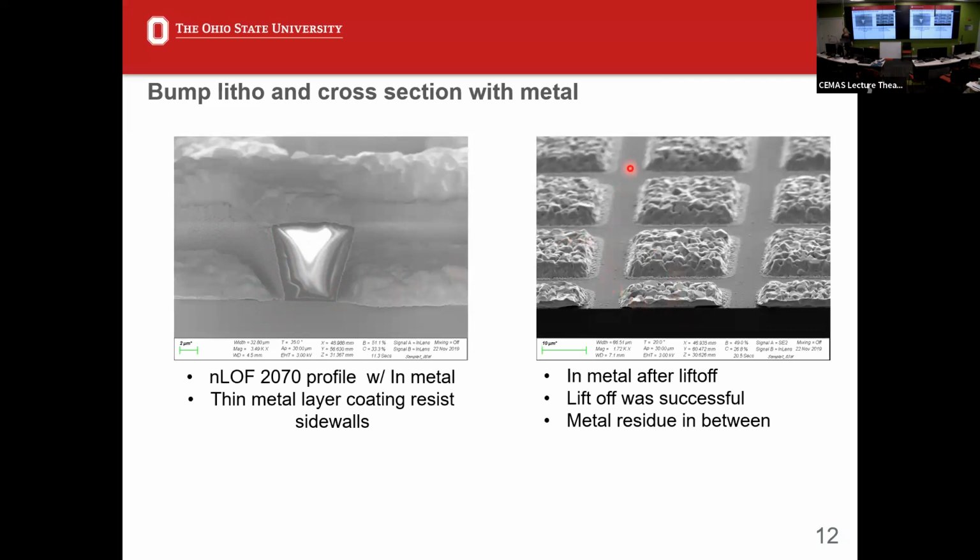The good news was it still lifts off. We have some residue in here, but the nature of indium is it likes itself, right? So when you do this reflow process and make that bump, the good news is as long as you pretty much have it right, you end up with these nice uniform bumps that you got here. So it's important for us to know what's going on.